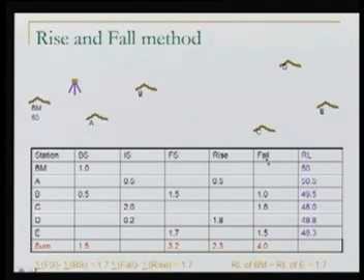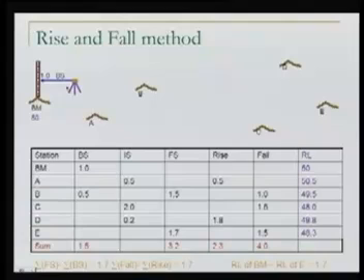The procedure is the same. We'll keep our level here. Please mind that the job we are doing in the field is not a different one. It's the same job. The only difference is how we are recording it. We keep our level, keep our staff, and take our backsight. Having done this, I will record this backsight here, as well as record that this point is the benchmark, so its RL is 50.